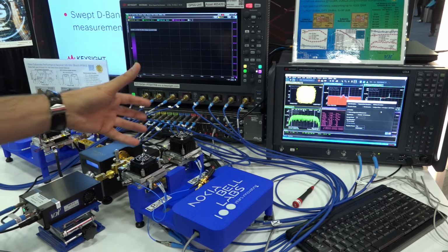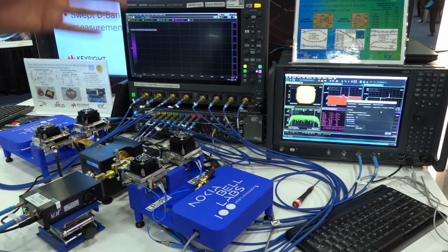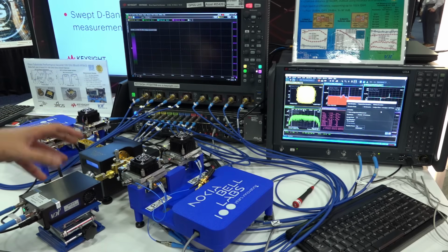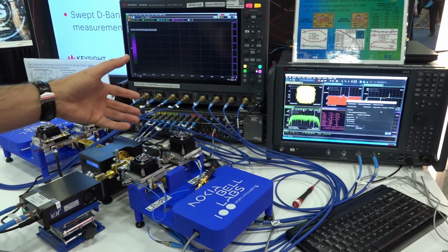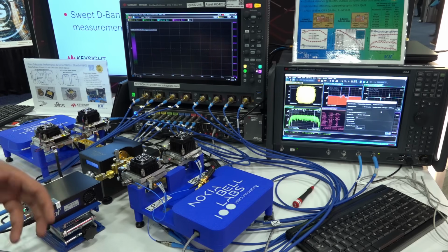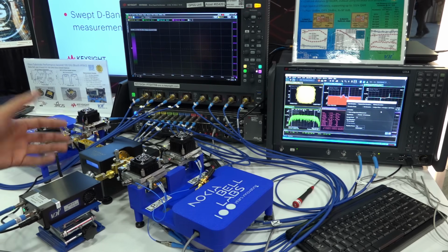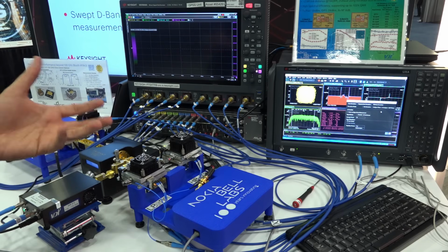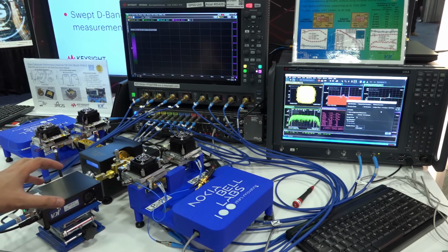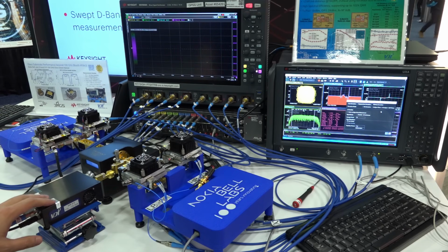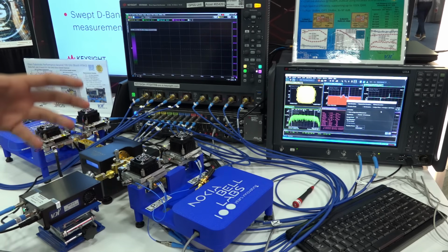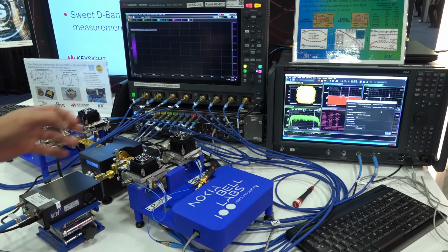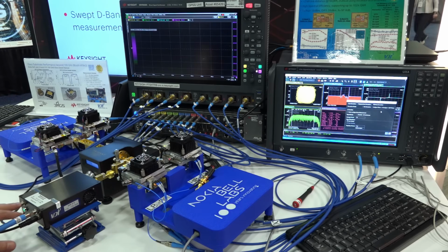Now, one challenge that comes from these kinds of measurements is that the higher you go in frequency, the noise of the device that generates your signal and the noise of the analyzer that's trying to analyze your signal may actually limit your measurement dynamic range. So there has to be some clever signal processing we can throw at this in order to remove some of those noise effects. Removing them allows you to understand where the impairments of the system actually are and where they are limited. So let me show you a quick look at the IQ noise cancellation on the instrument.